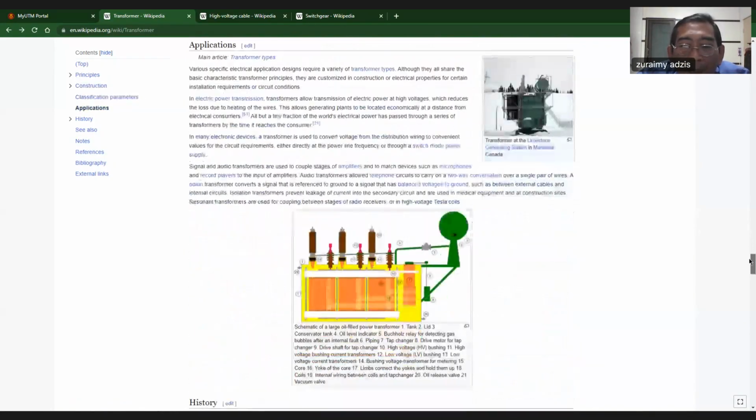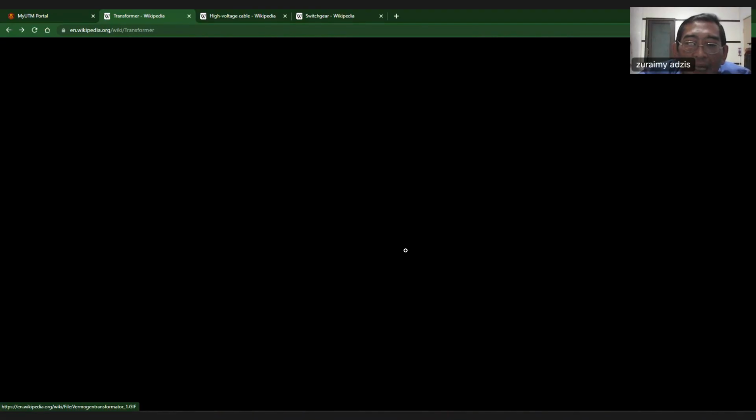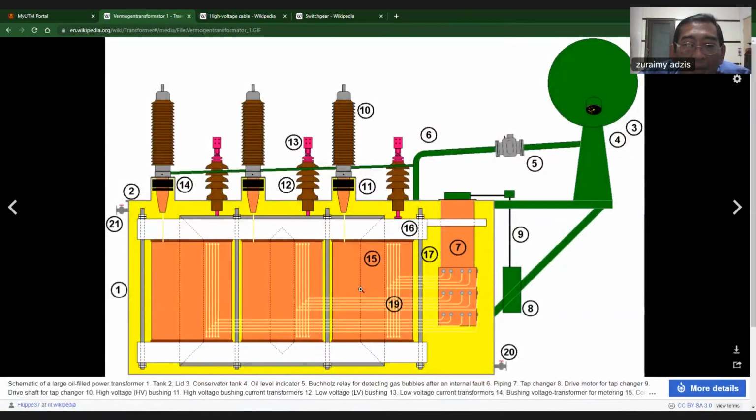Okay, application. So this is a sort of cutout of a transformer. Okay, you can see here oil everywhere. And then the windings, you have paper. So paper and oil. But if the oil is depleting or leaking over here, then the oil level will become less. Even with the reserve tank, the oil also cannot be supported. So there will be pockets of air here that will reduce the insulation by a lot, and surely breakdown will occur. We won't like that situation.